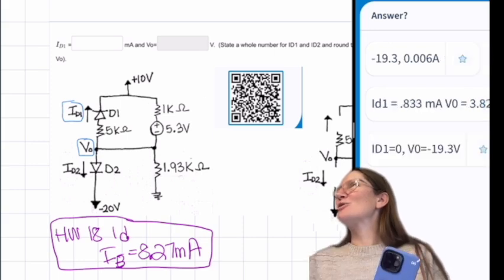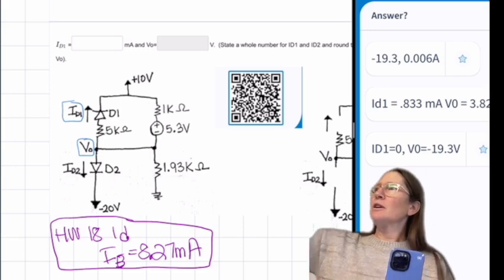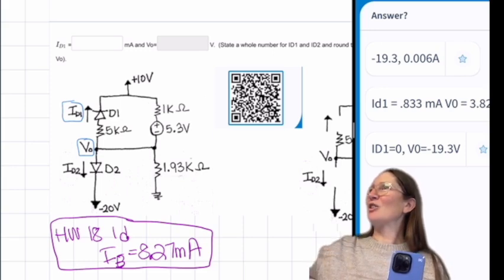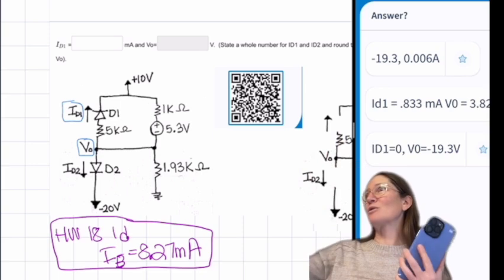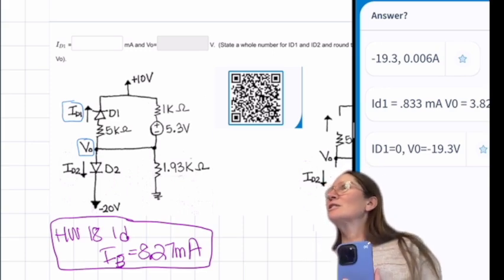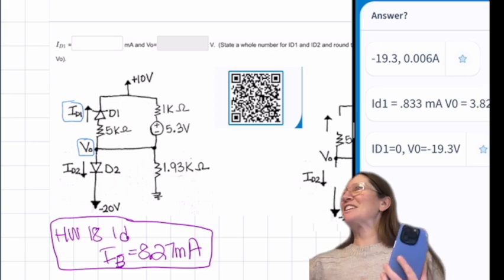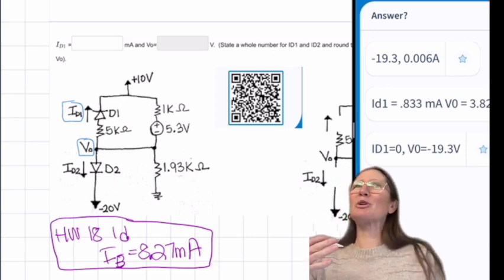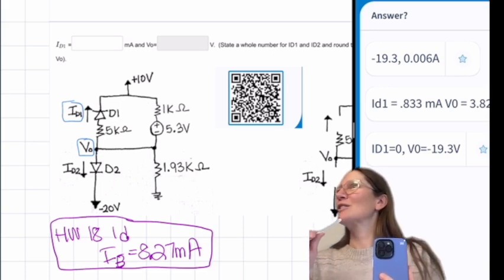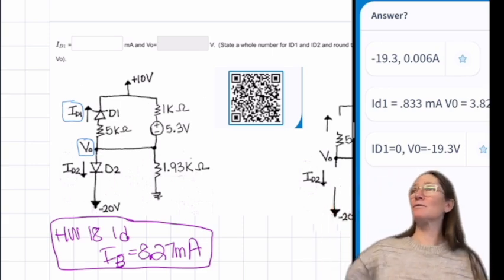So it depends on what the solution did. Remember I was saying you can approximate it by just doing IE times the voltage there. It depends if you're ignoring the contribution from the base. The answer is assuming that there's nothing really coming from the base, so it will be a little bit off, but as long as you're close to that number. My philosophy again is get some hand calculations, then go use a simulator to get the actual values. They're going to be more accurate than your hand analysis. So as long as it's close, it shouldn't be off by a lot.